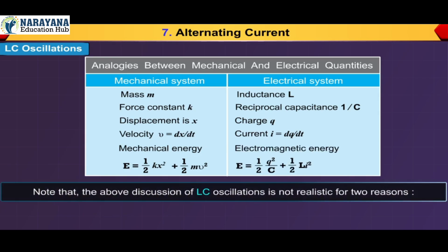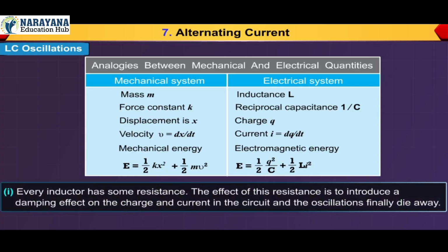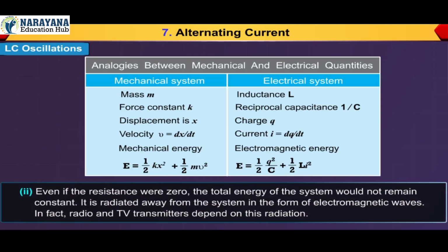Note that the above discussion of LC oscillations is not realistic for two reasons. Number 1. Every inductor has some resistance. The effect of this resistance is to introduce a damping effect on the charge and current in the circuit, and the oscillations finally die away. Number 2.